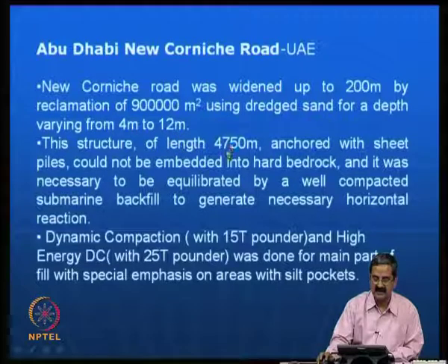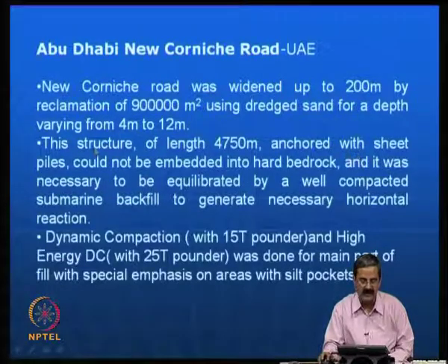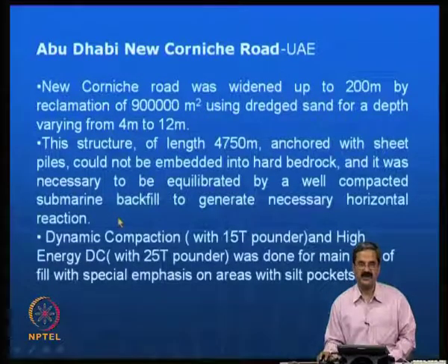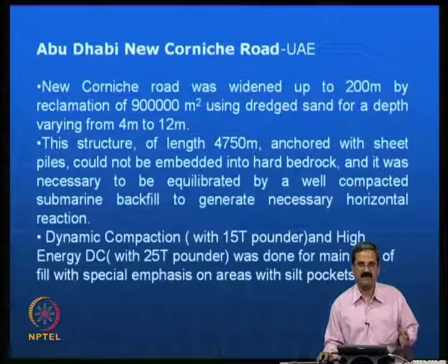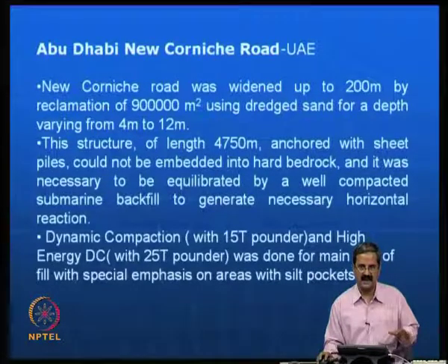The length of the structure is about 4.75 kilometers, and it should have been anchored with sheet pile walls, but it could not be embedded into hard rock. It was necessary to be equilibrated by well compacted submarine backfill to generate the necessary horizontal reaction. Actually, in sheet pile wall construction, if you have a well compacted backfill behind the sheet piles, the earth pressures coming onto the retaining wall are much less, so you can optimize the design in a proper way.